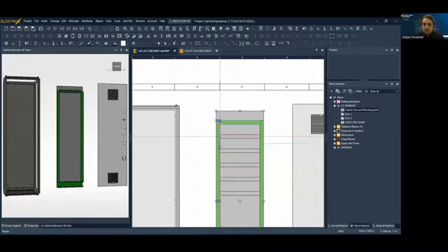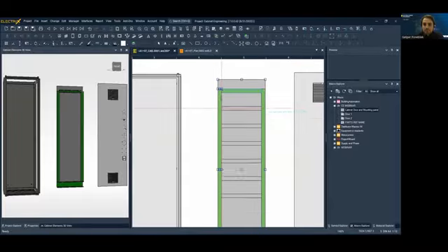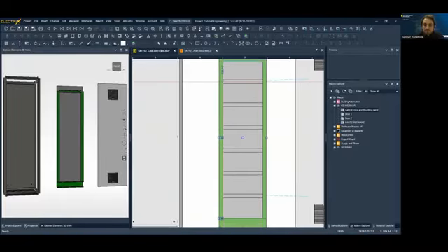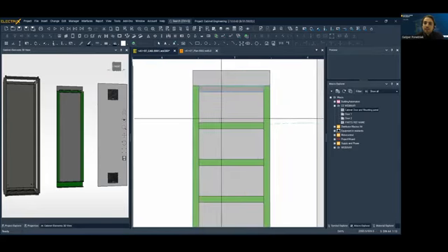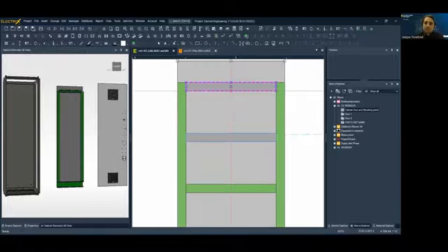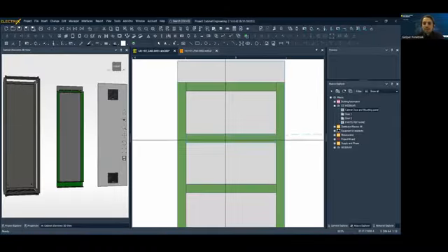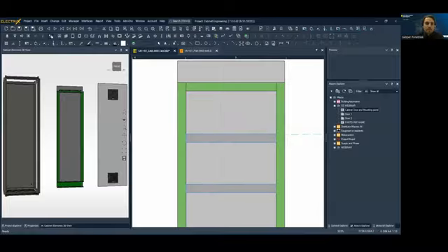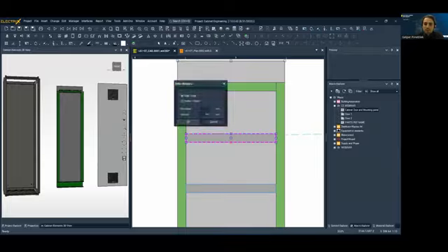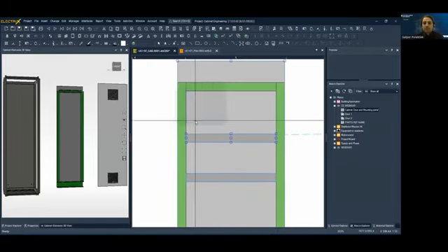because we need 7 of them here, like this. And then you can see here we can also make some specific space between these cable ducts. Let's say vertical distance would be 200 millimeters, and then other distance here we can also place, it's like 145 millimeters.